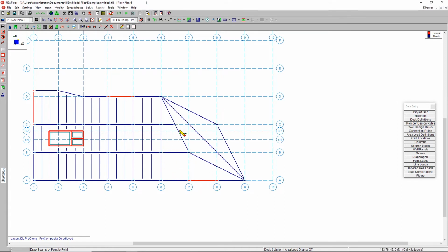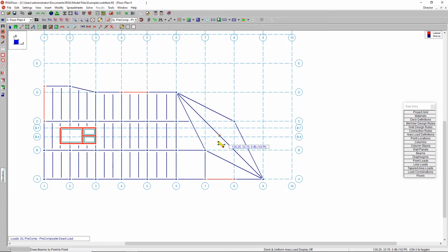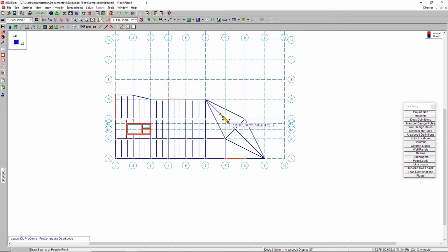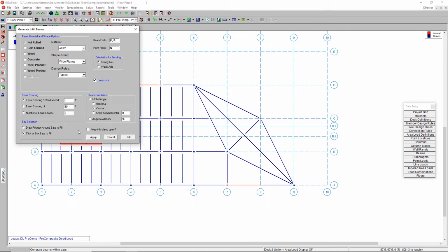So we've got here, I'm framing this in, and then I'm going to go ahead and put in my infill framing. So the infill framing, I'll just connect these guys there. Oops, I'm going to actually connect them so that they break. So I'll keep off the continuous spans. There we go. Okay, so the infill framing here is going to be a little bit different. I'm going to go horizontal in this direction, horizontal here, and then I'm going to go vertical, actually in this diagonal direction. So you have a lot of ability to do those things.